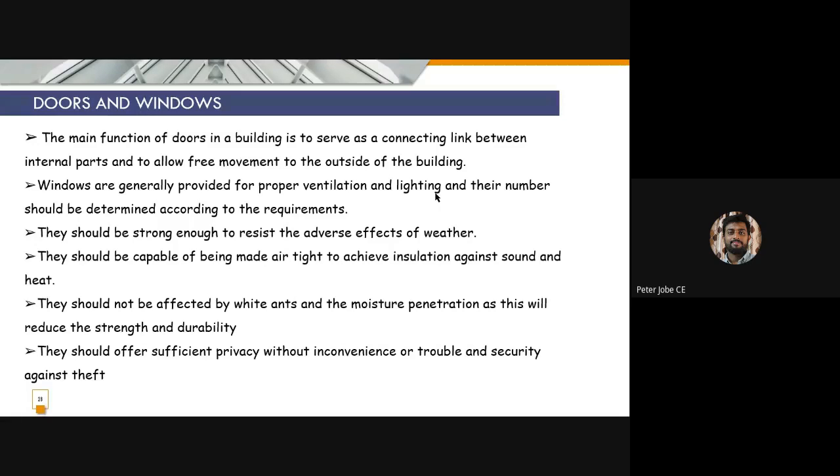So if you look at a library, it is always recommended for a library to be in a dark place. Understand? We should not keep our book racks near windows or doors or open areas, because once the sunlight enters our building, our books and paper can get damaged due to the effect of sunlight. If sunlight is constantly falling onto our books, what will happen to our papers? They might get damaged. So it is always recommended for a library to be in a dark space where outside light is very limited. There should be some light, but it should not fall directly onto the book racks, so that it cannot damage our papers. So according to the function of that particular room, the ventilation and lighting should be adjusted. All these things will be done using doors and windows.